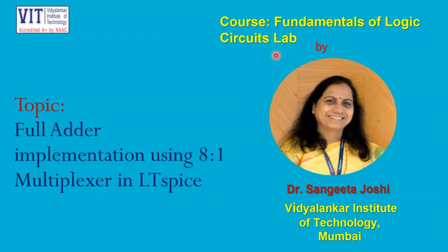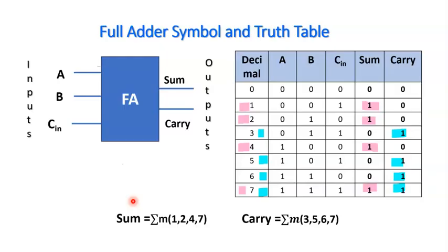In the last video I demonstrated the operation of the multiplexer in LT Spice, and today we'll try to understand how a full adder can be implemented using an 8 by 1 multiplexer in LT Spice. To start with, let us recap the fundamentals of the full adder.